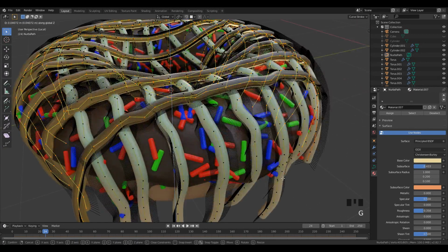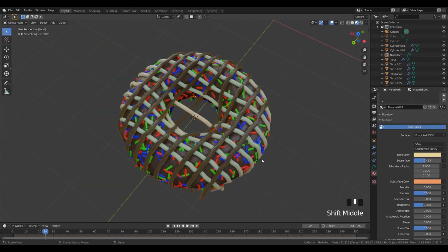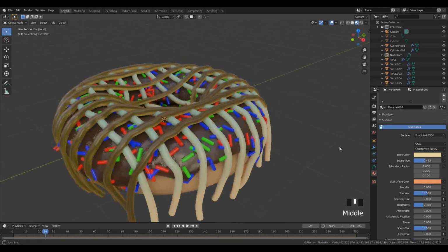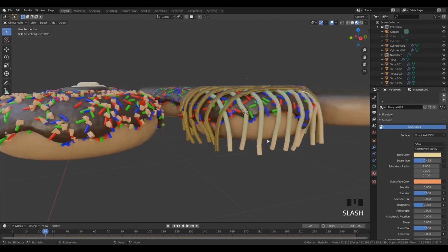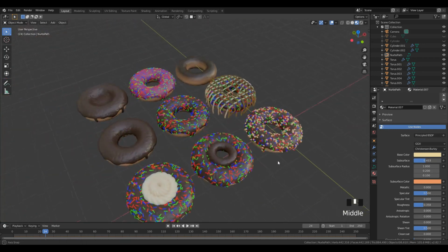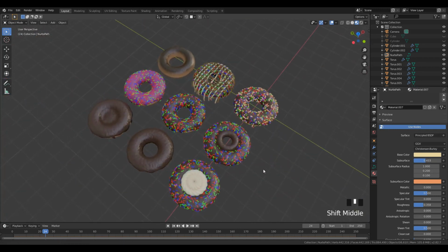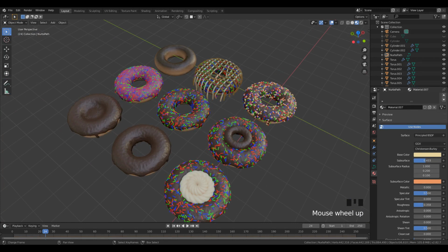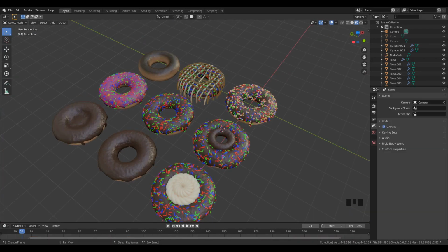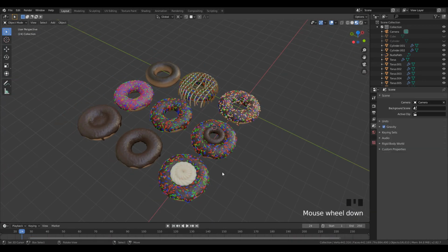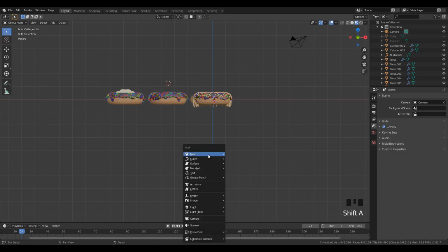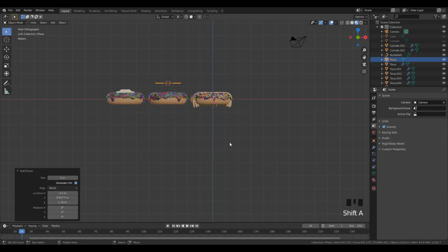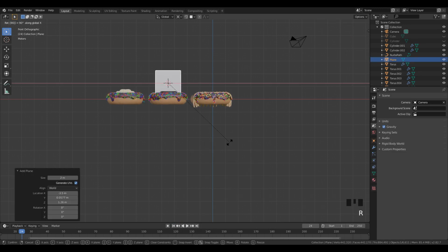After that, in edit mode, inverse the selection and move this selection slightly on the z-axis to make it appear on top of the other meshes. You can also use the same path tool or Bezier tool to create the cream of the topping of the mesh. To create spiral shaped cream, change the viewport to orthographic view by pressing numpad 1 and add a plane to the scene and rotate it by 90°.